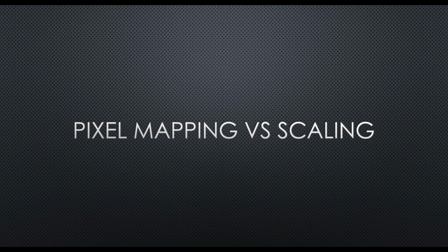So pixel mapping versus scaling, what are the main differences? Pixel mapping is basically mapping every pixel of your output signal, whether it be your computer, DVD player, or any sort of digital player that's supplying the signal, to the actual LED screen. They all have specified resolutions, such as 1920 by 1080 being HD resolution.